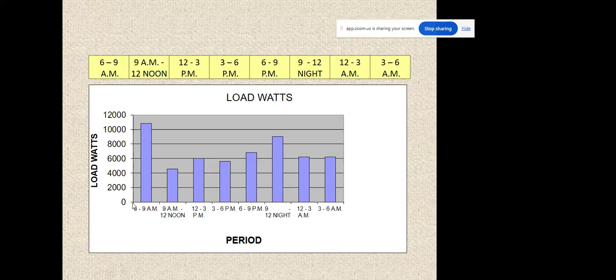So for 24 hours, what is the load pattern? That is important. From that, we can calculate how much is the utilization of the DG set, whether a standby set is required, whether only two sets are required, one for the night and one for the day. So for combination purposes, these patterns must be studied.